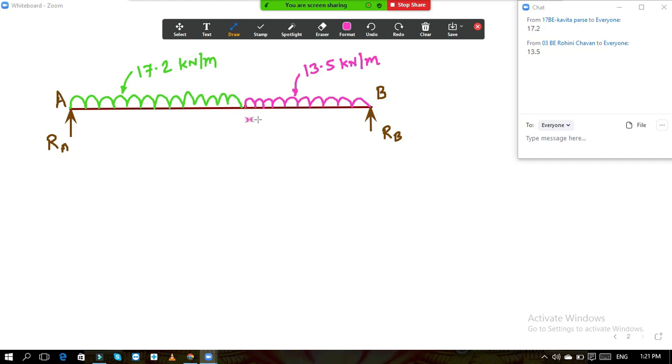First of all, this distance up to this point, it is 1.51 meter. Okay. Now what was our going length? Our single tread is of 0.3, into, we have provided how many treads? We have provided 9 treads, so 2.7 is our going length. And plus half of the width of support you need to add into that.